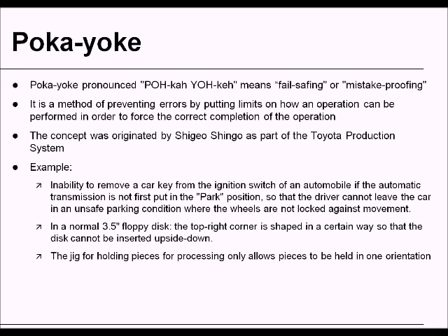That's error-proofing and inspection all at once, because humans forget, and inspection's only 80% accurate. So 1 out of 5 times you could be trying to pull your keys out and the car's in drive. So what they did was make it impossible for that error to happen. They built quality into the process versus inspecting it in.